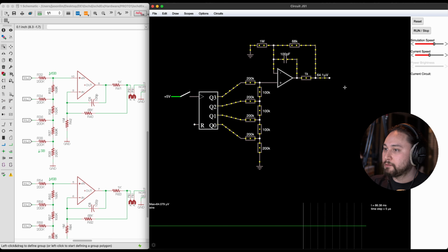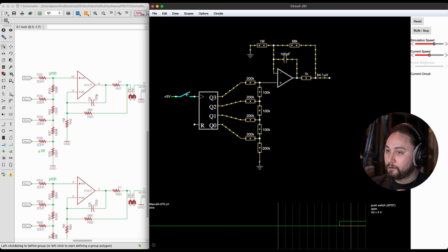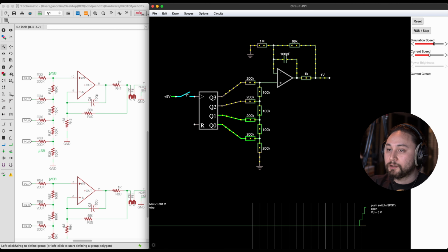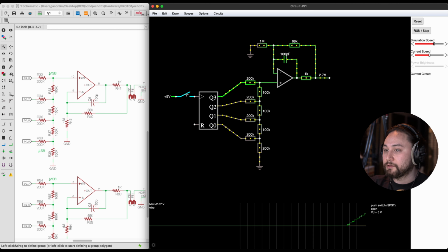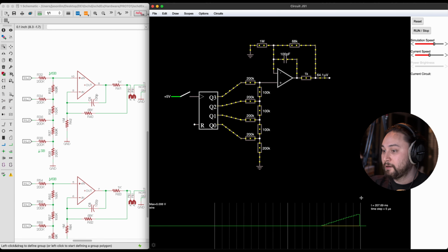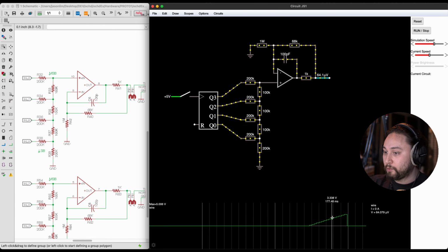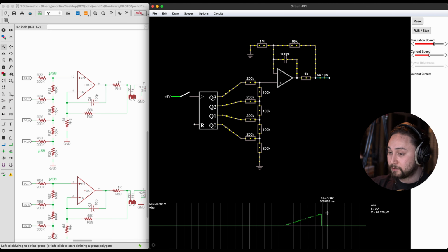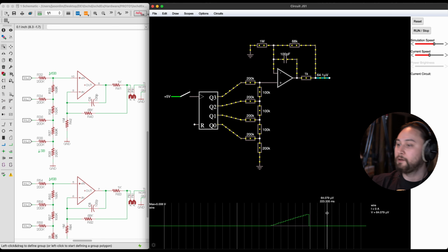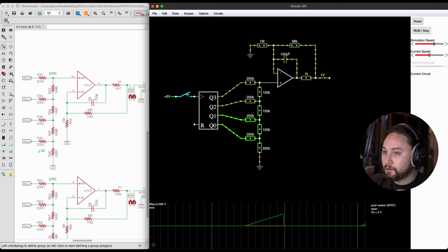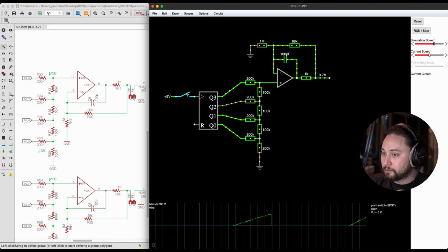signal amplitude. So let me show a scope on this, and I'm going to step up and I'll try and keep it a consistent rate. Here we go. 2, 3, 4, 5, 6, 7, 8, 9, 10, 11, 12, 13, 14, 15, 16. And that's our result. We have a steppy, but quite distinctly recognizable ramp. So that's going through all the discrete voltage steps of a 4-bit counter.